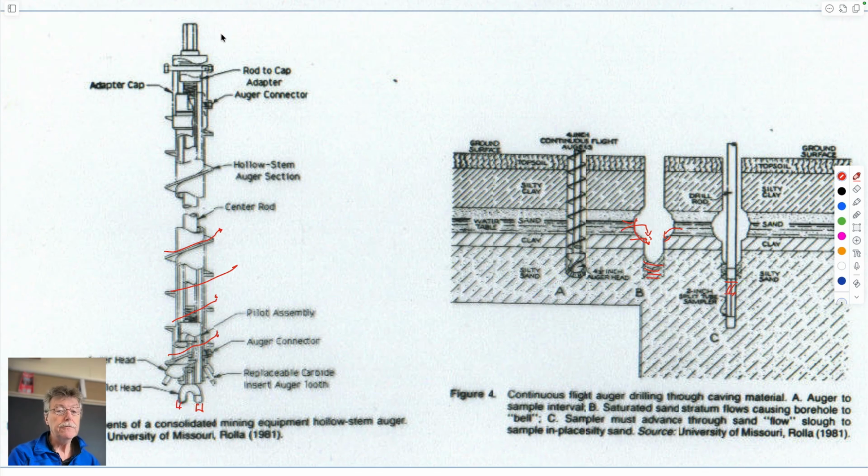You can sample it at the surface if you wish, but the whole idea of this arrangement is that now when you're down at depth, what you can do is pull out this central stem, solid stem. It comes along with this cutting shoe, and it leaves the bottom of the hole open.